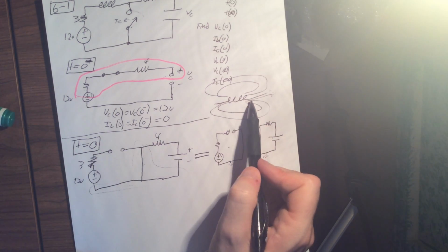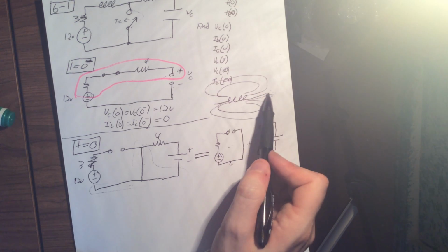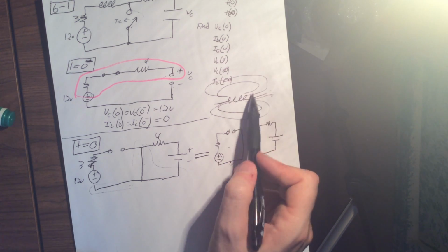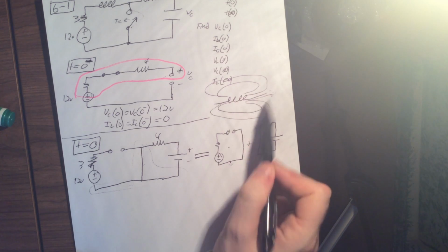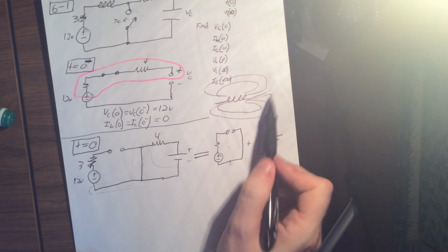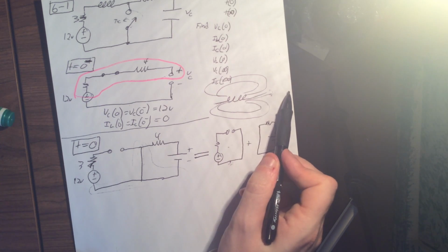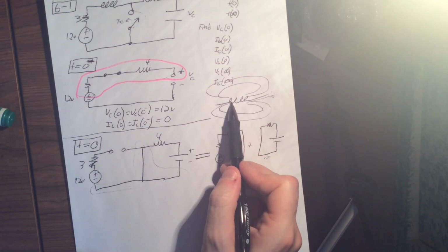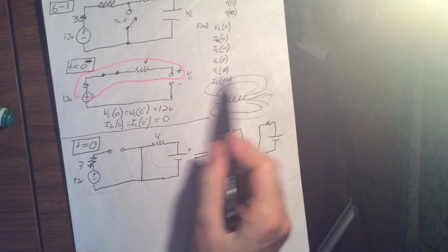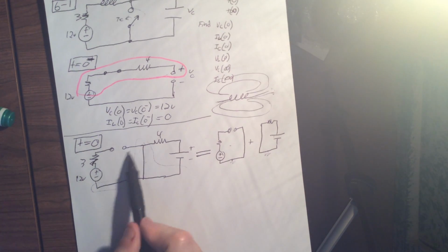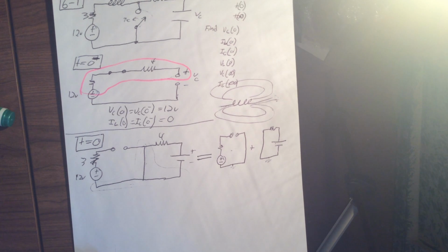But if I stop, all of that field has to slowly decrease, because again, inductors resist change in current. As I let go, all this current starts draining off. But coming into this, all that current gets sucked up in this field, starting to make these field lines. And that's why, for the start, we've got this open circuit here.